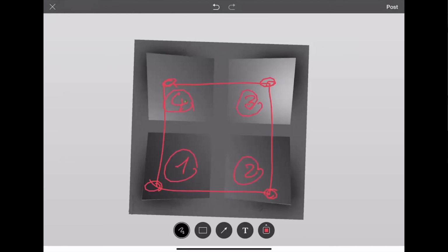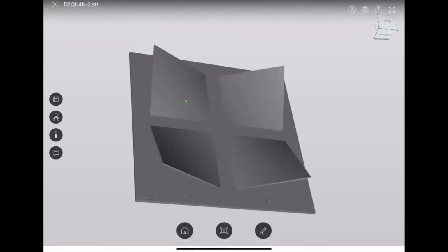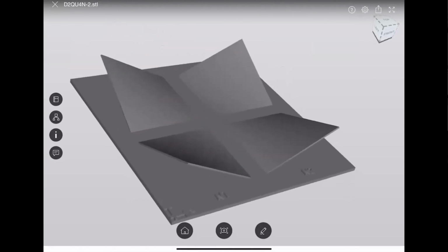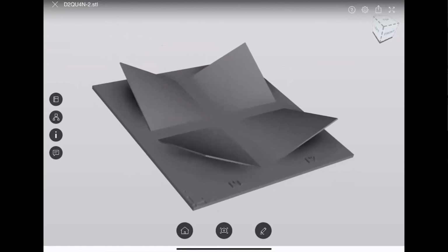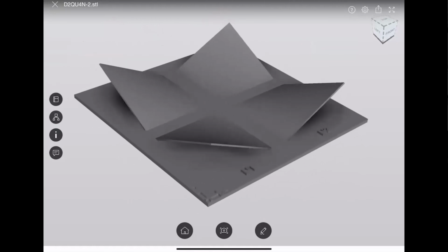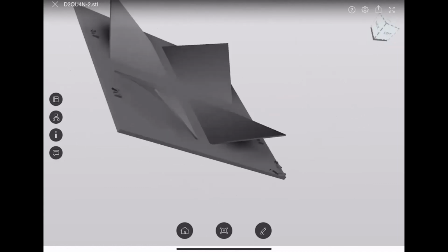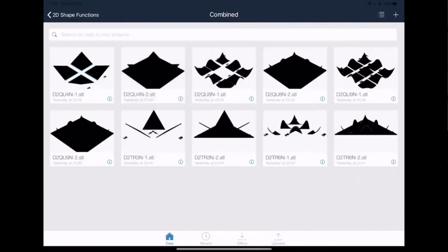Now on this plate, I am showing exactly those shape functions in the same order that we numbered them in our notes earlier, and you can see what they do. First of all, they are geometrically similar, but N1 is 1 at node 1, 0 elsewhere, and N2 is 1 at node 2, 0 elsewhere, and so on. So these are the 4 shape functions for the linear quadrilateral element.